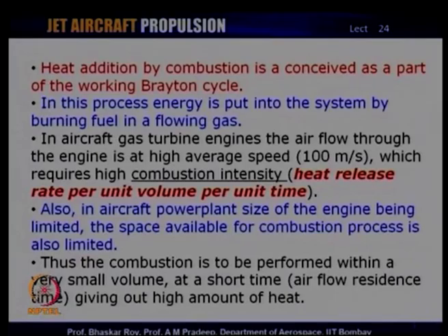Now, the aircraft gas turbine engine has the problem that the air flow through the engine is at an average speed of close to 100 meters per second. Now, that is a pretty high speed, actually speaking, which requires that the combustion intensity is very high. That means, in a very small time, if you have 100 meters per second average speed, the residence time in any of the elements of aircraft engine is a matter of fraction of a second.